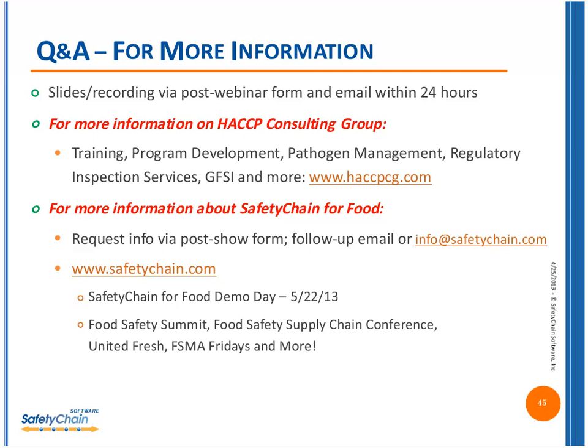Quite simply, verification is, did you do what you promised to do? Go out and see if people did actually conduct cleaning activities, for example. Did they clean the equipment? Validation is, did it work? So is it clean when they're done? You can conduct a verification by looking at paperwork to see if people filled out their records, or you can watch people do what they do. And then validation is the piece where you test either by visual or some other type of sampling or inspection systems to see if a process worked.